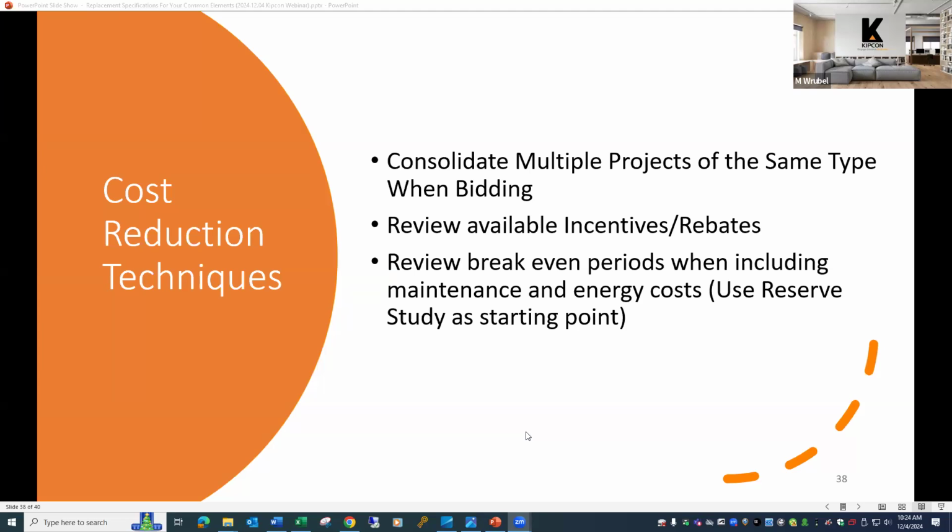So on the reserve study, oftentimes they can be, I don't want to say removed, but you can suspend funding for new segmental block retaining walls for a certain period, because they just have a very long useful life. So even though they have a larger cost when being constructed, over their useful life, the cost for that particular material is much lower.